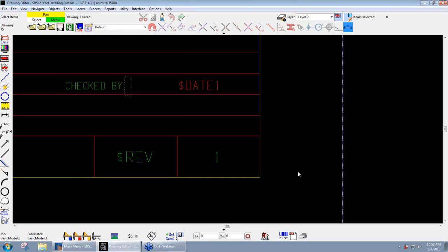It would find the drawing name that you were saving in any label, and it would replace it with the new drawing name. Now that could cause problems if you had dates or company name, any contract number, any sort of information. If that label matched the drawing name, it would get updated.